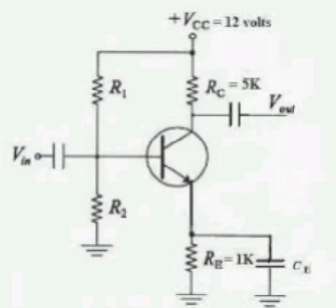We have voltage source Vs equal to Vm sin omega t plus 5 in series with C. From there, one resistor of 400 kilo ohms goes up and the other goes directly to a BJT. The connection from that BJT is connected to the source of the MOSFET, and then the gate to 400 kilo ohms is shorted, and M2 of the drain is shorted to VDD of 10 volts. Output is taken between M2 and Q1, that is the collector of the transistor to the emitter, the source of the MOSFET. The output Vout is taken.